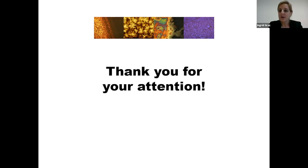I'm working at the moment with some companies that are interested in impact protection. If you assume something hits a surface very hard, and you manage to transmit the heat you generate, the dissipated energy, very fast to trigger this instability. And if you look at the 4 milliseconds that we achieve, this is about the time you would need for protective measures in automotive, like inflating an airbag. So if you were able to translate the energy of an impact to heat to trigger this instability, that would be sufficient.